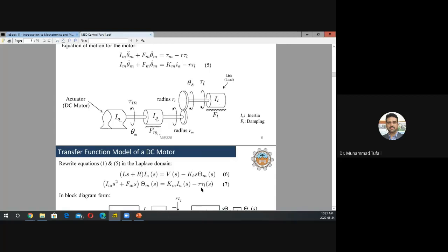minus R, and let's say this is a time varying load. So this is T_L, we can write it as a function of s. This time varying load you can think about like, let's say you're closing and opening the bar at the park gate. So it has quite considerable inertia, and there is gravity acting on it, and that gravity is not constant throughout. It depends on the angle that it makes with the axis of rotation. So that's one example of the load torque.